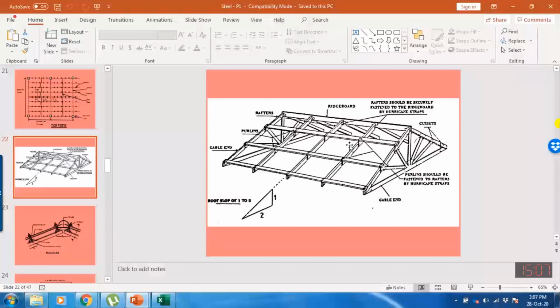So it means that if we are not providing the sag rod, then we need to select a very heavy section which may have a very large moment of inertia in the y direction also. So to make the design economical, we select a lighter section in combination with a sag rod. A sag rod may be provided as only one sag rod at the center, or two sag rods, one at each third point. So at the start, we can take the decision about the sag rod.